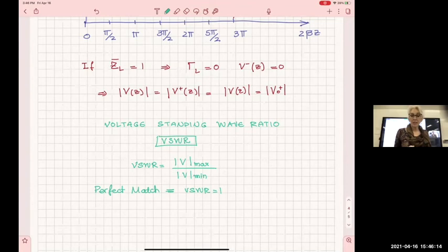On the Smith chart. So now if we have a few minutes, I would like to go with Don. We are going to see on the Smith chart, now you have to think about what is the worst, all right? But on the Smith chart, it's going to come immediately. What is the worst? The worst case for matching is if your load is only reactive or open or short. Why? Because your reflection coefficient gets its maximum value. How much is the maximum magnitude of the reflection coefficient? 1. Wherever it goes, comes back.